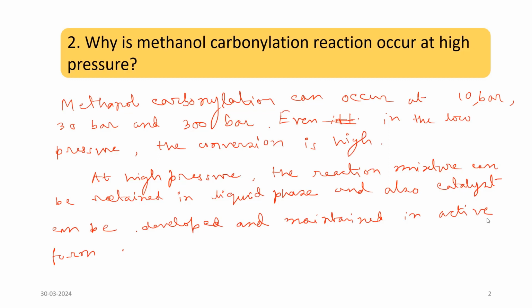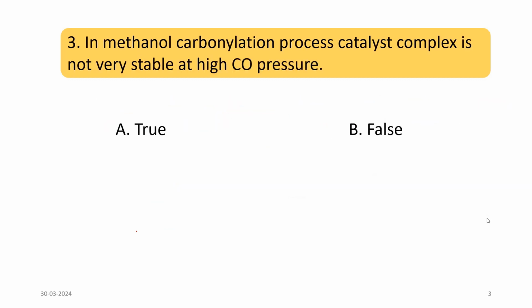That means it will not decompose at high pressure, but at lower pressure it might decompose. Then if the catalyst is decomposed, what is the point of doing the reaction, right? So for these two reasons, the mixture is kept in liquid phase and the catalyst can develop its active form at high pressure. That is why we have to maintain this methanol carbonylation reaction at higher pressure, even if the conversion is achieved at small pressure. Okay.